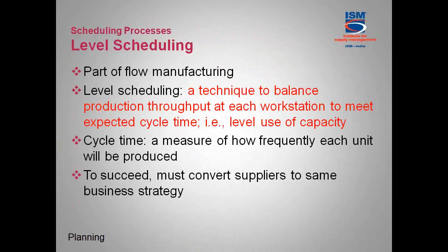Suppose the cycle time at one particular machine is 100 units per hour and another machine is 120 units per hour. So I will do the level scheduling by keeping some buffer before the second machine, where the cycle time is much less.